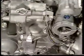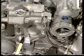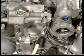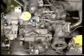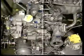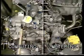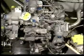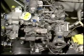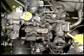The fuel control mounts on the front face of the fuel pump and is secured by washers and self-locking nuts. It is a hydromechanical control consisting of 2 major sections: the metering section and the computing section. Contained within the metering section is a fuel filter assembly, a throttle valve, and a minimum pressure and shutoff valve.